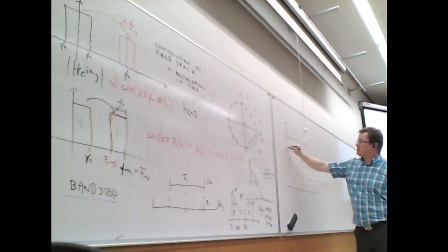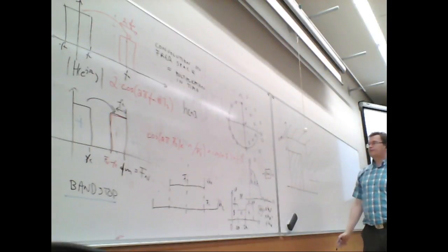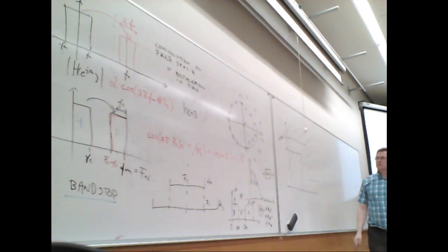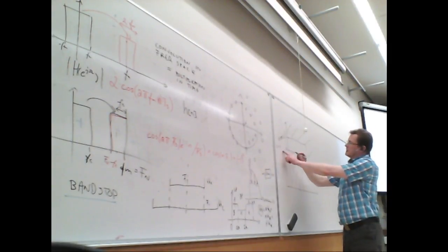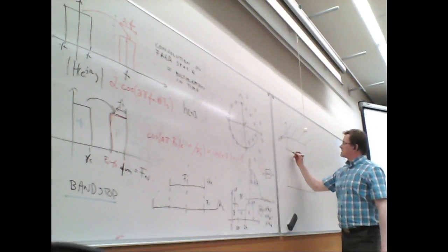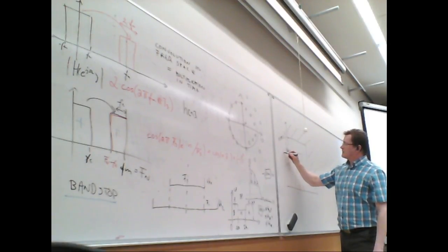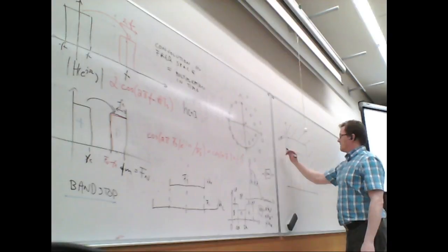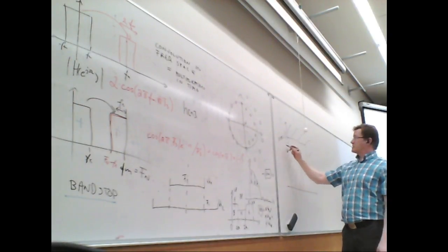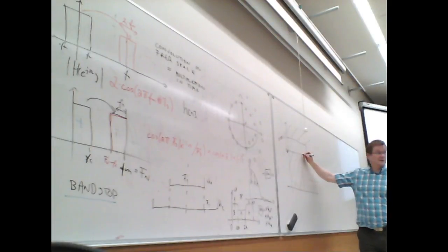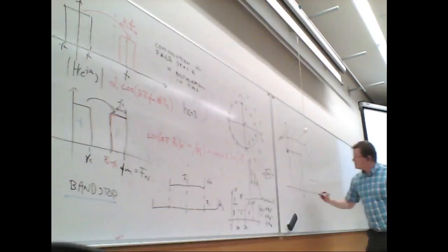This is the ripple of the desired response. If there's 0, then basically for 0 ripple systems you would have minus 3 dB as your cutoff level. But for any other, then you would use the ripple for the cutoff frequency. So that point actually defines the cutoff rate.